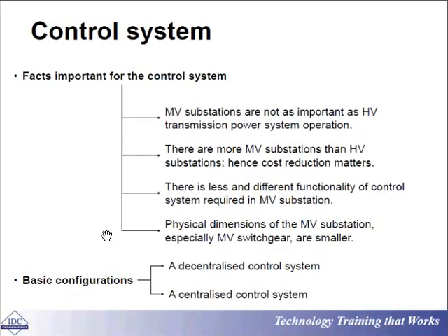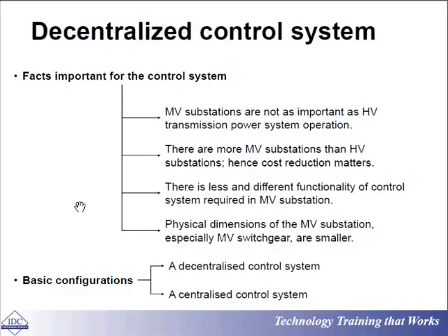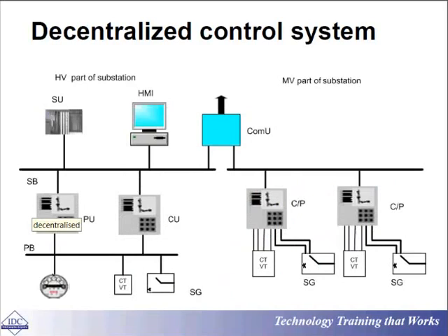So one of the most important things to consider is, in terms of automation, would you like to have a centralized control system or a decentralized control system? That's up to you. Centralized is more simple, everything is something like wireless, okay? But if you lose that center or centralized control, you're finished, okay? If it is decentralized, well, more wiring, more effort, not as user-friendly, but at least you are not going to lose everything. So this is an example of a decentralized control system.